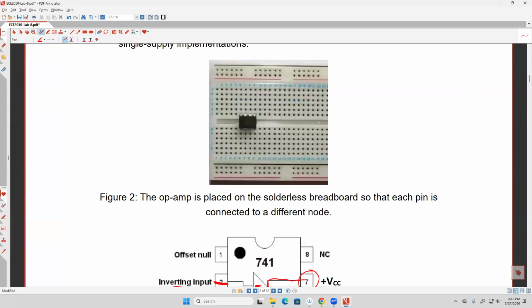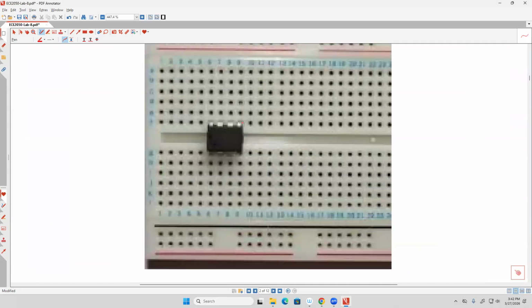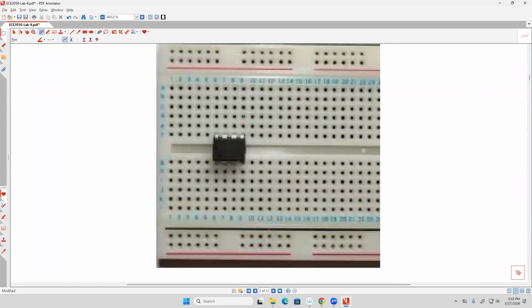Number 2, which is very important: how you are going to connect it. As I told you before, for the breadboard you have, this whole column is just one node. If you connect a wire here, internally they are connected actually. So if you make a wire here and a wire here, it's actually a short circuit, because it's already internally connected. For example, pin number 7 is here. If you want to connect anything to pin number 7, you can put it here, here, or here. They are the same.